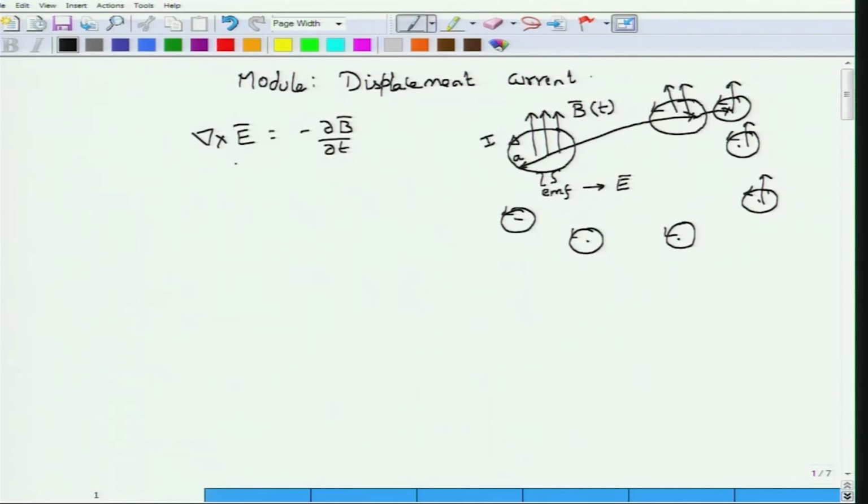So you look at this equation of curl expressed in the point form for Faraday's law, and you would see that if the B field is varying with space and changing with respect to time at any point, it would create a space varying electric field, correct. So the field around this would be varying depending on how much the magnetic field is changing. Here you have a space variation of the electric field related to the time variation of the magnetic field.